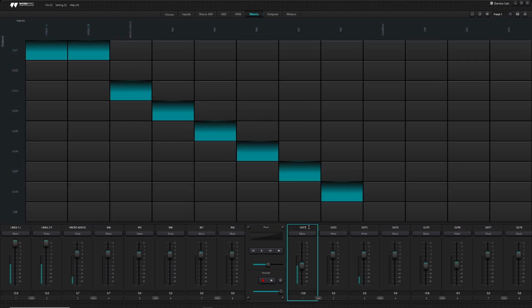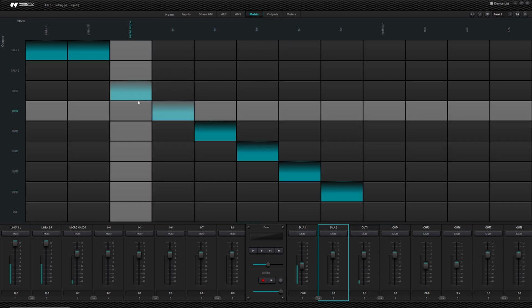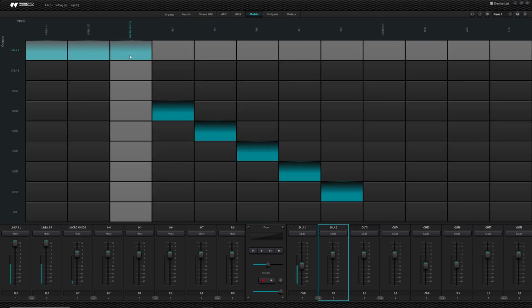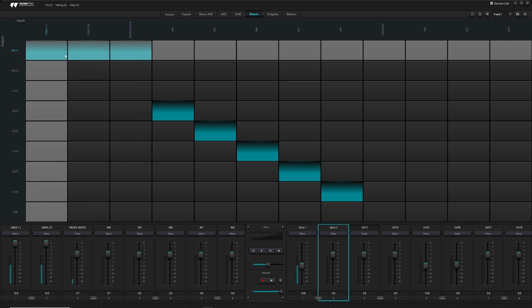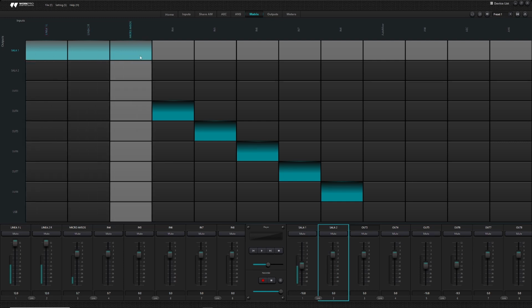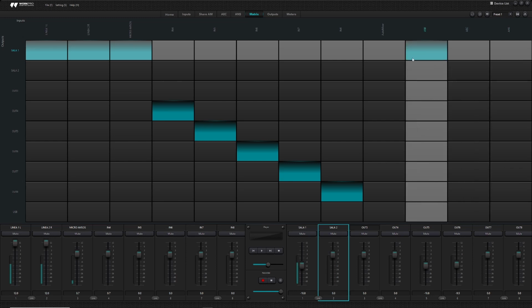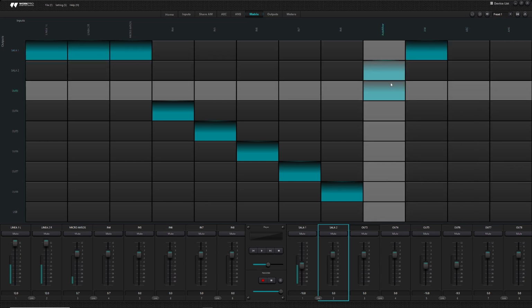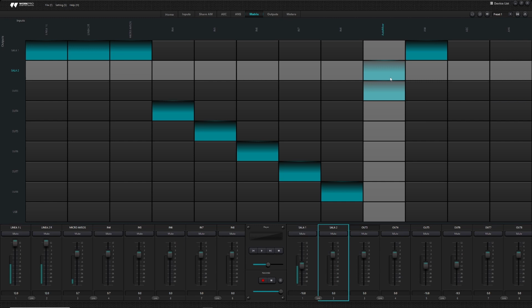This output, named 1 for example, can be renamed as we want. In this case, room 1, output 2 would be room 2. We will also include the announcement microphone in this room 1 output, and could also switch in this matrix its various functionalities, like the USB player, or have the AUTOMIXER send us that audio mix it is producing to different outputs.